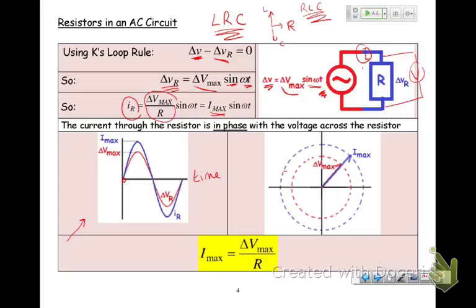What's the reactance of a 5 Henry inductor when 5 radians per second AC is applied to it? So my reactance of my inductor, my XL, is equal to, what was that? That was the linear one, wasn't it? Omega L, which equals omega, which is 5, times L, which is 5. Ooh, shame on me. 25 ohms.